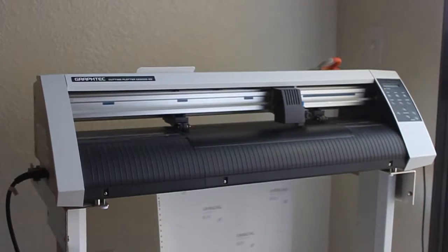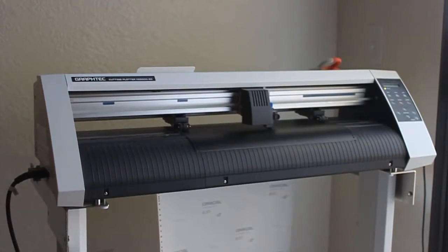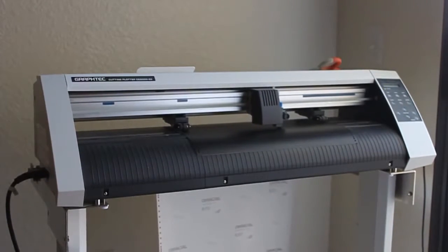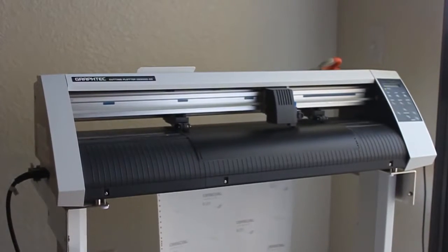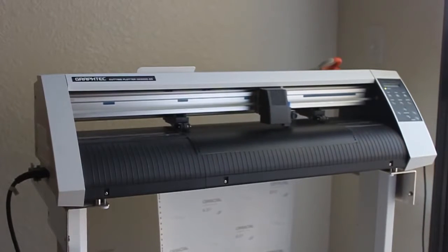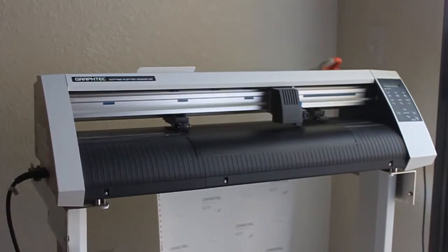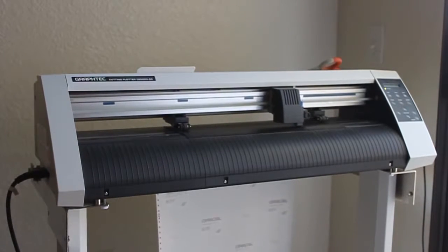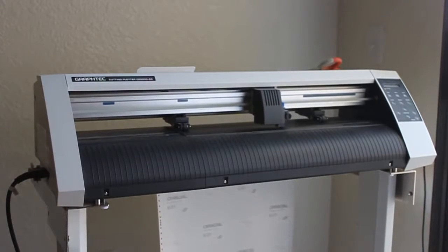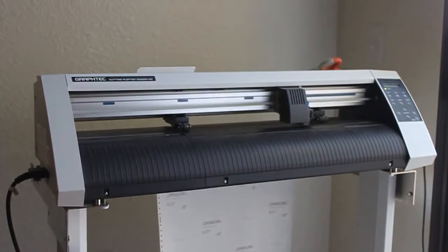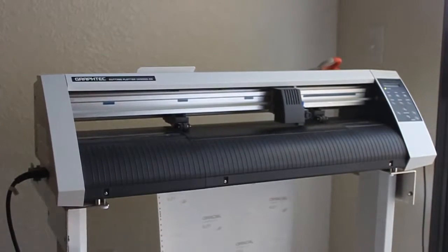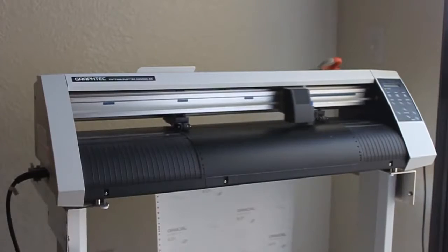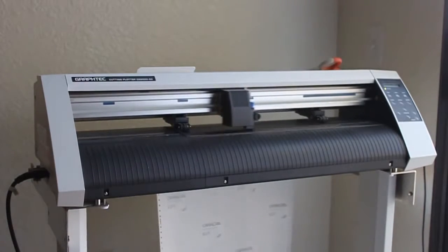So now, as you can see, the vinyl cutter is actually cutting out the graphic that we designed. It works just like a printer. Instead of there being a print head that ink is coming out of, it's actually a small little knife in the head on the vinyl cutter, and it's actually tracing and cutting out all those lines that we created in Illustrator to create our graphic. And then next we'll go ahead and weed out the extra vinyl, which is taking out all the excess vinyl that we don't need to have our graphic, and then we'll have it to put on something, and we'll take you through that process next.